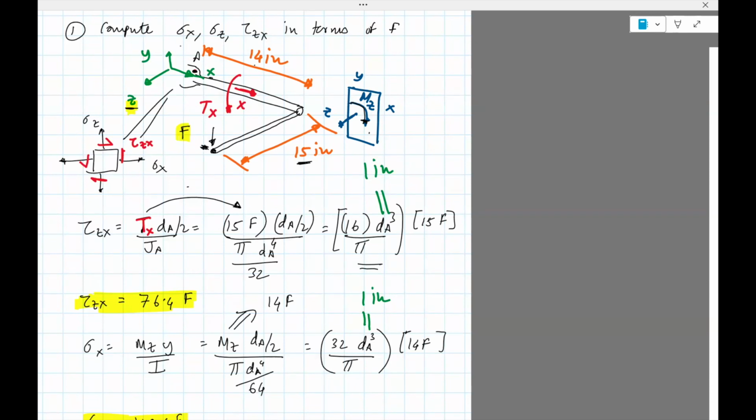But let's say that I did introduce a force this way. Let's say I put a force here, F1. Do you think there'll be a shear stress at A if there was a force in the direction of Z? Okay, this is a simple way in which students make a mistake. Even though it's a force in Z, the shear stress at A due to the shear force is 0.